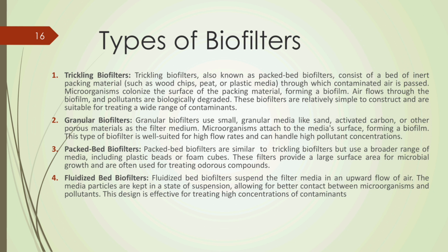Third is packed biofilters. Packed biofilters are similar to trickling biofilters but use a broader range of media including plastic beds or foam cubes. These filters provide a large surface area for microbial growth and are often used for treating odorous compounds.